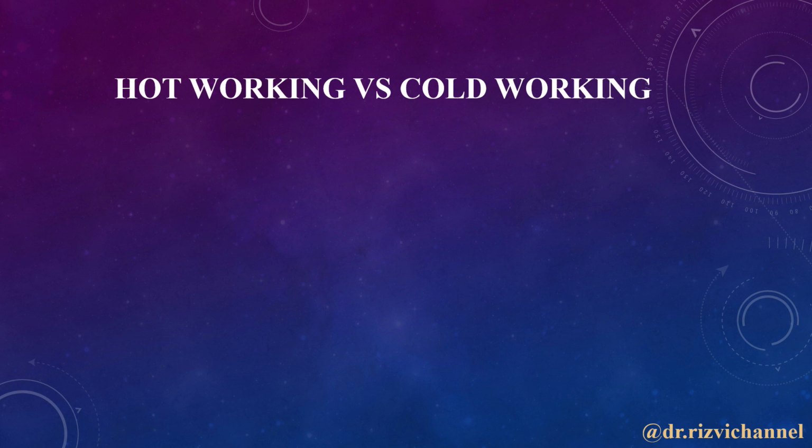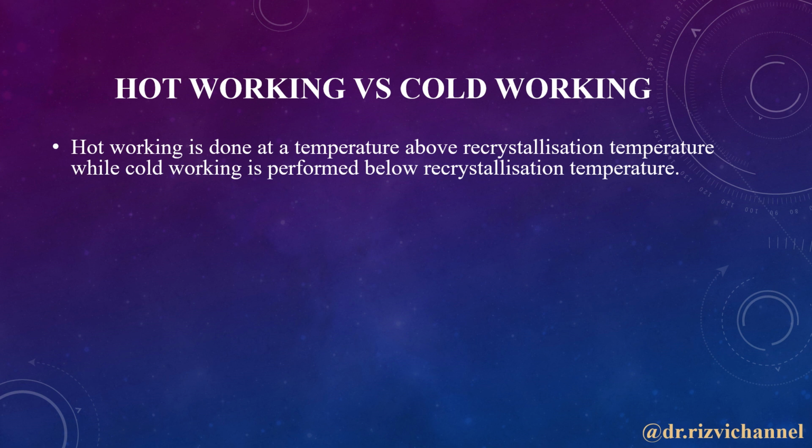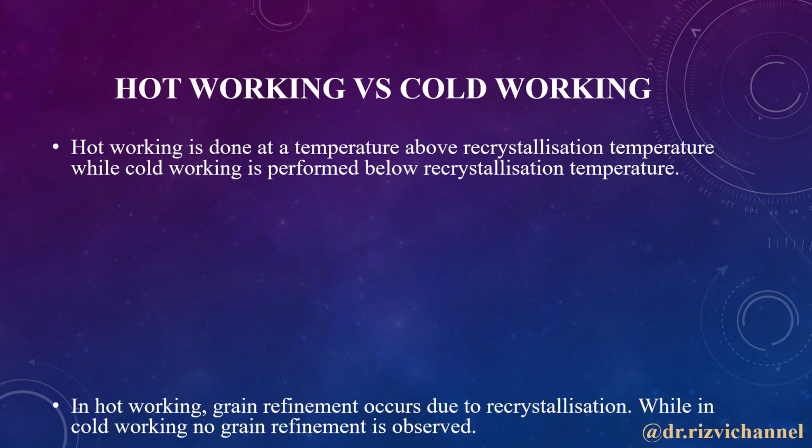Now we'll discuss hot working and cold working processes. They are dependent upon the recrystallization temperature. When we are working on some material above recrystallization temperature to deform its shape, then it is termed as hot working. And when we are performing deformation below recrystallization temperature, it is termed as cold working process.